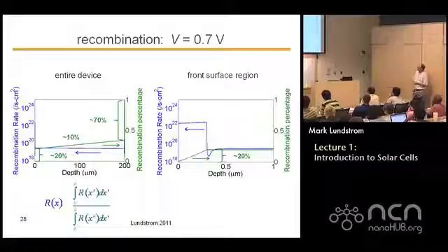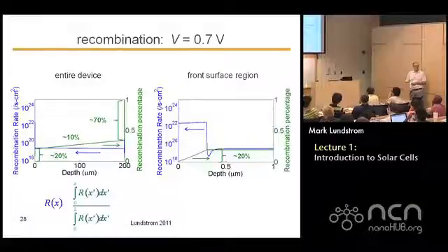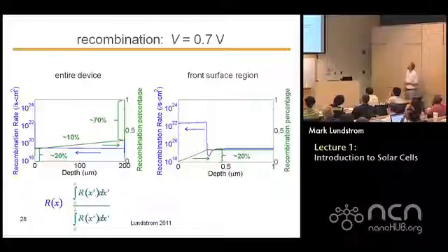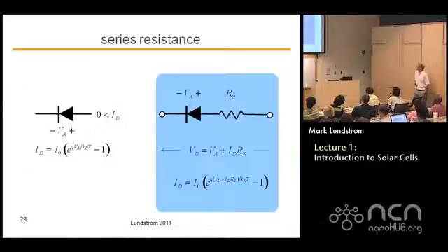And if I look at the front, I can see that there's a significant amount of recombination in the front, 2 orders of magnitude bigger than what's happening in the P region. That's because the lifetime is very, very short in that very heavily doped material, so it's recombining very quickly. Okay, so there's a lot of information that we can get out of that, and that's sort of the subject of the talk tomorrow. I will mention that roll-off region.